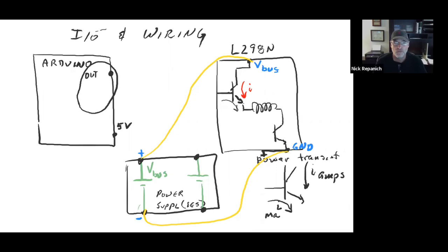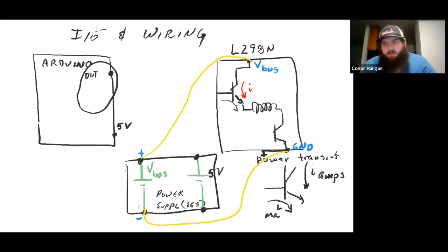You can't really tell. It could be internally pulled up. If power is off and you measure it in a state where it has internal switch control, a voltmeter is helpful when you want to know if there's something wrong or what's going on. But in general, the way you find out is to keep reading. Is it 5 volts in or 5 volts out? And if it's 5 volts out, oh, it's a supply. We might be able to use it down here. They might have put a 5 volt supply for you to use. And if they did, what's the next thing you want to know about that 5 volt supply? What its maximum current output is. Exactly. Imax.